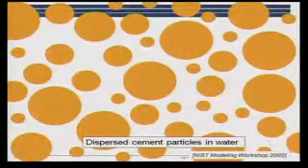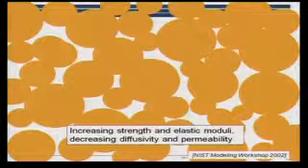You can also see the change here where we start to have dispersed cement particles in water. That's from a workshop at NIST in Gaithersburg, and increased hydration, and here. And when the hydration takes place, you can see that you have more and more solid and less of the pore volume. And you have an increase in strength and a decrease in permeability. And this is normally what we want.